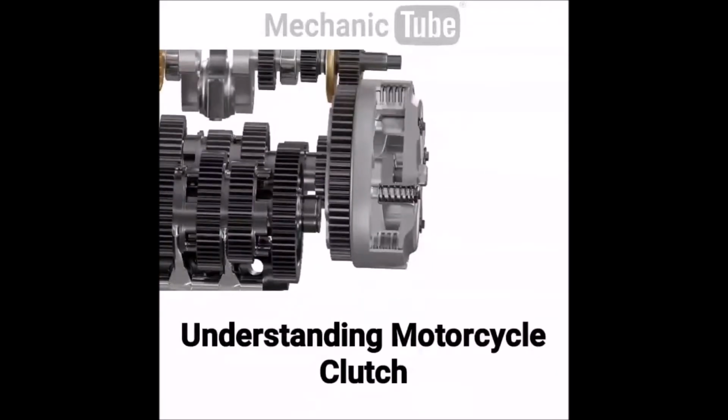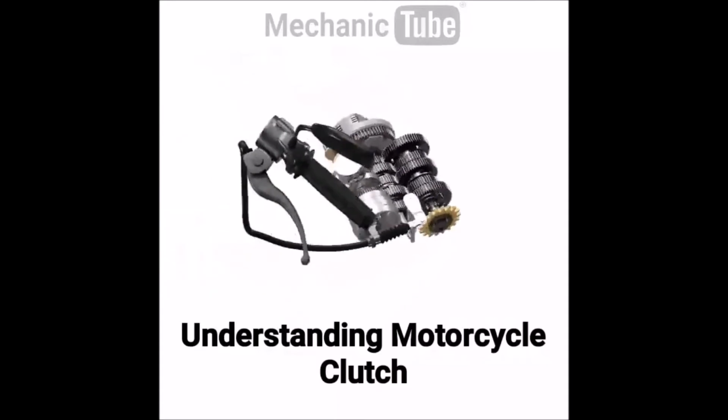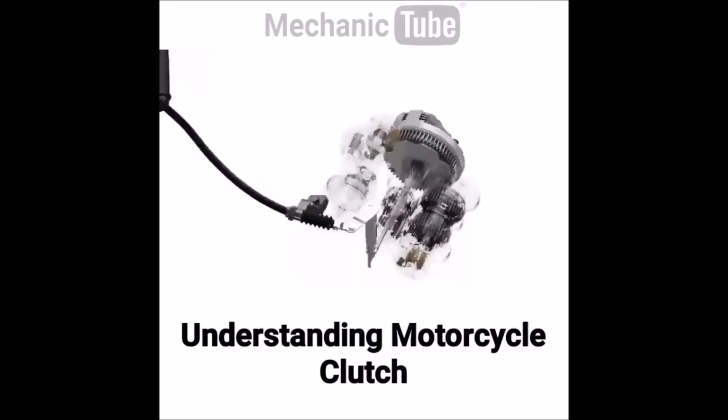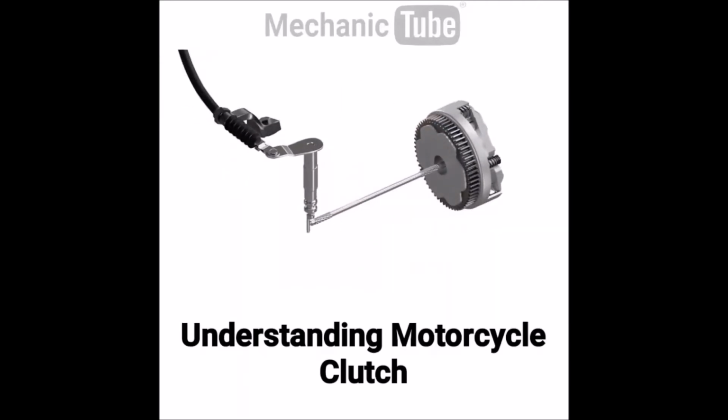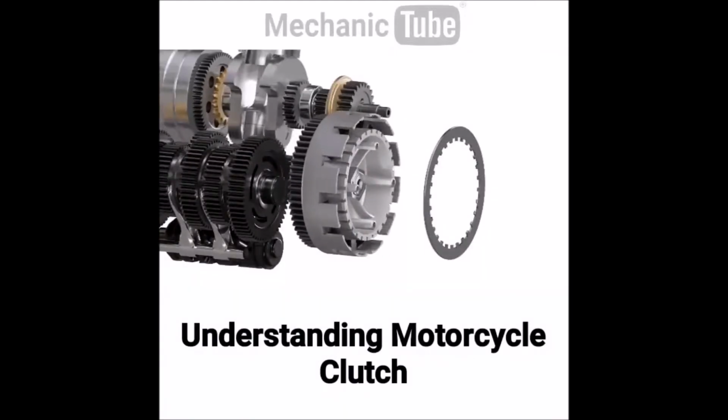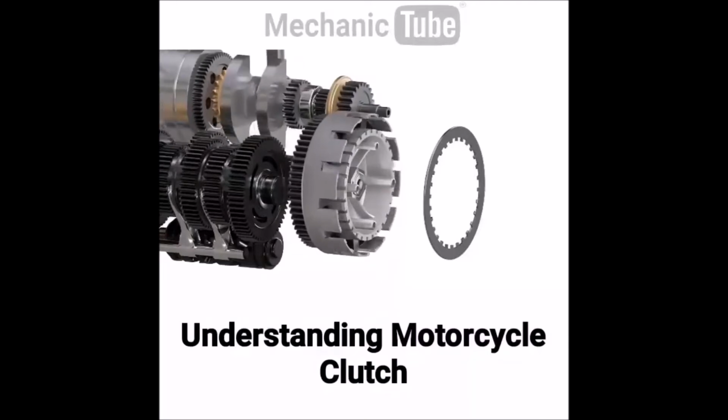We can release the pressure on the clutch pack by pushing the pressure plate outwards. We can control this pressure by pulling or releasing the clutch lever. As the clutch lever is pulled or released, a cable or hydraulic system rotates an actuator arm as shown in the animation. The plate spins with the clutch basket but doesn't affect the inner hub.